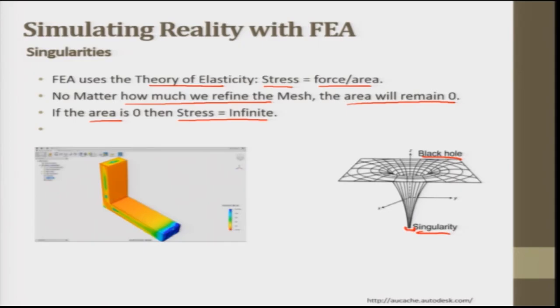Singularity can be confusing because it may cause an accuracy problem inside the model, which implies a problem with visualization, because singularity extends the range of stresses. So it has extended the range of stress here. This means that smaller stresses can appear to be negligible. Let me put a number. This is 1,000,000 units of stress. So this is only 2 units. So this looks to be negligible. So this is why singularity is a problem here.